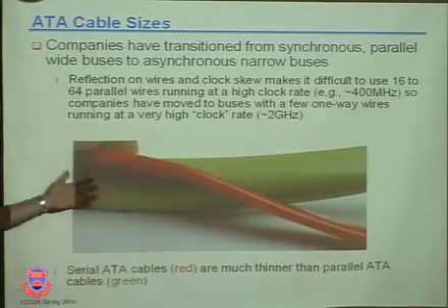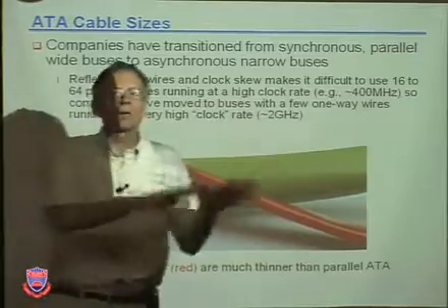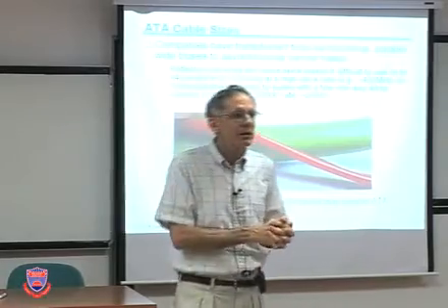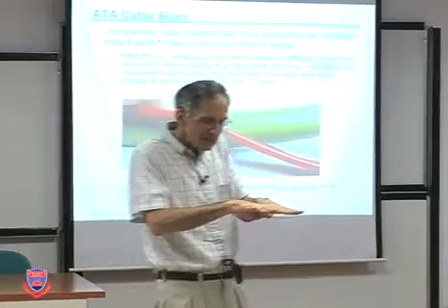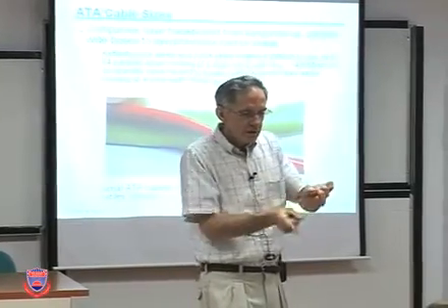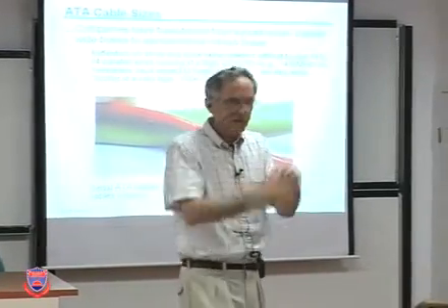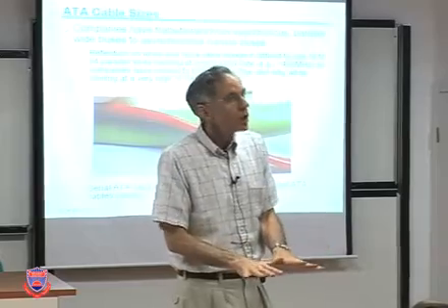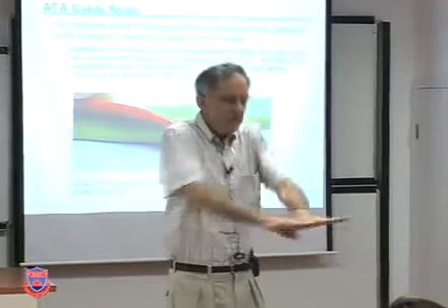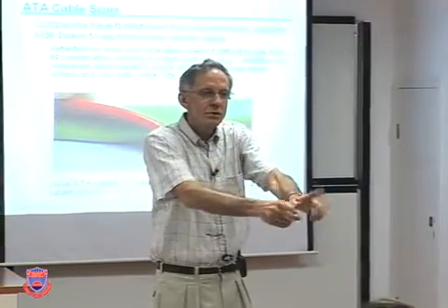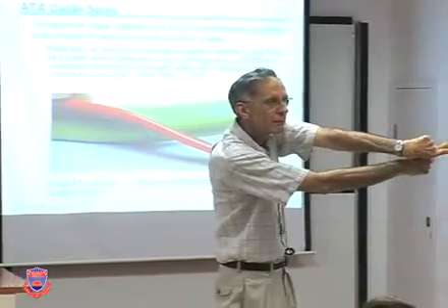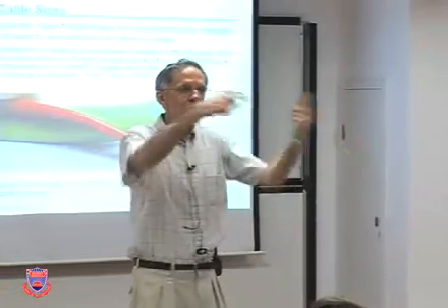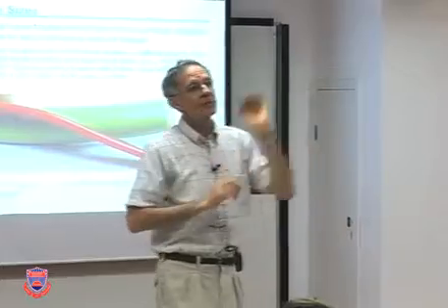And you might think, oh, well, then more bits in parallel will be better. I'll get higher data rate in parallel ATA. In fact, you're completely wrong. Turns out when you get a lot of lines in parallel, their crosstalk, the electromagnetic signaling that they affect each other with, makes the clock rate have to go low. Slow it down because of all this parallel hardware. As soon as you allow a serial bus with just two wires and you are allowed to twist them, then the electromagnetic crosstalk cancels and you can go at really blazing high speed rates.